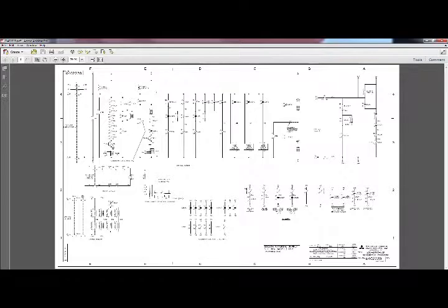Now remember, the coil is just a little solenoid, and when you run current through there, it creates a magnetic field that causes that little plunger to pull up, and then that disengages the stop that's holding that shaft that we saw in the picture, and then it shifts and the breaker opens. The whole thing accomplishes its purpose.